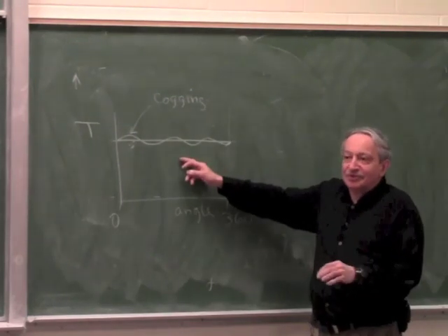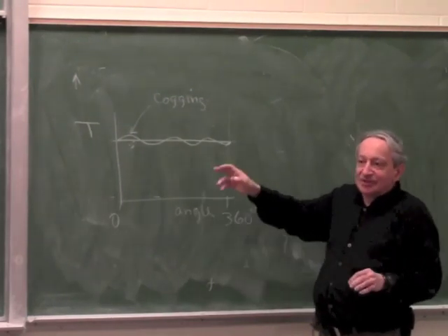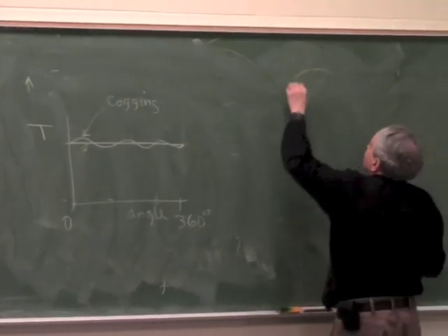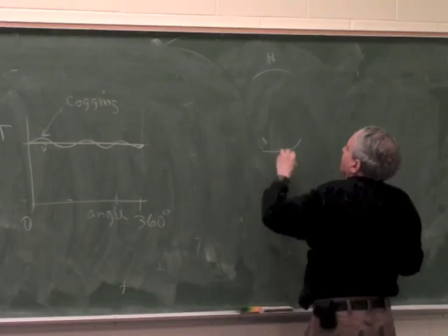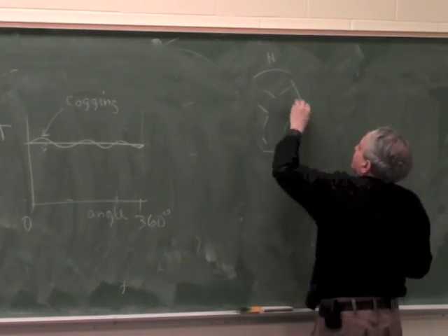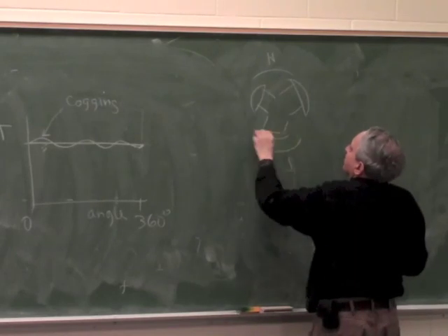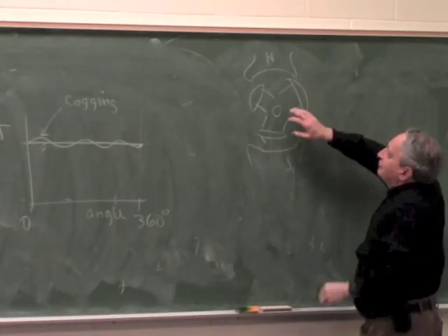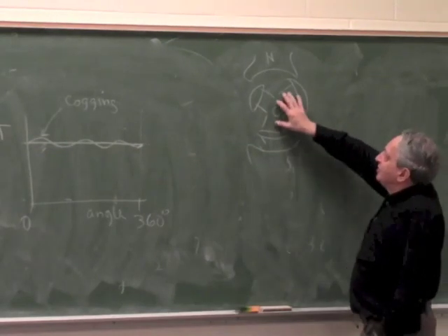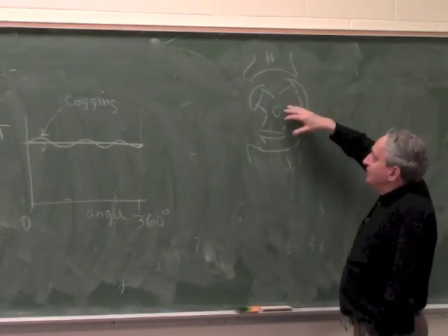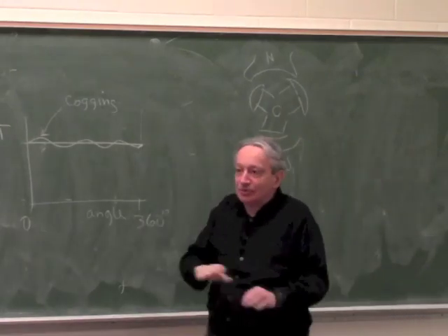In DC motors, it's the same, because the air gap changes. Right? If you have a PMDC with N and S, and you have an armature like this with 3 poles, you also have variations in the flux, because the flux is a bit different when the armature is rotated a bit, okay? So there are also flux changes, so this problem appears in all motors.